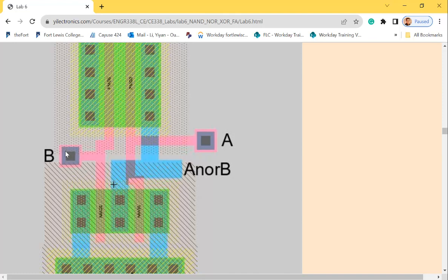And also you see this is the via, and the gray area here is the red metal 1. That's how they made the little contact for you. It's something the library can directly use. You know what I mean? So it's for this thing. If you grab from the left-hand side of the library, it has a pink area which is a poly, and it has a via, and it has a metal 1. So the gray area is the metal 1.